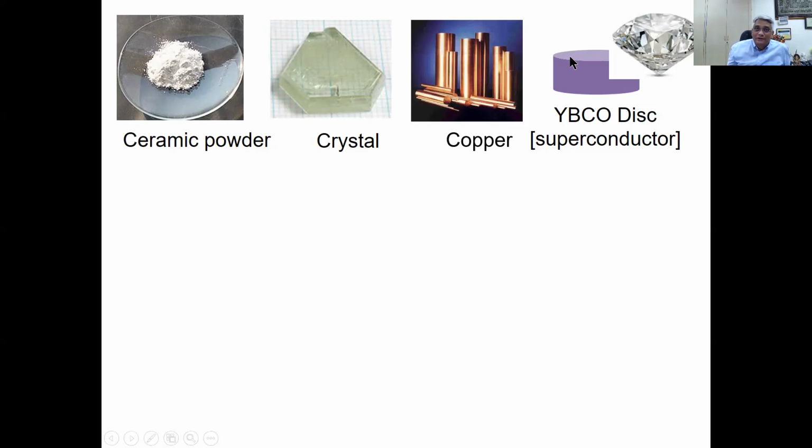So which also means that thermal conductivity not only comes from the contribution of electrons, it comes from something else, because diamond being an electrical insulator, there are no free electrons there. So here, in the case of diamond, thermal conductivity arises from the contribution of phonons. The phonon contribution is so strong that even though there is no electronic contribution, the phonon contribution completely predominates. Its electronic contribution is 0 here, whereas here it's both electronic and phononic contributions.